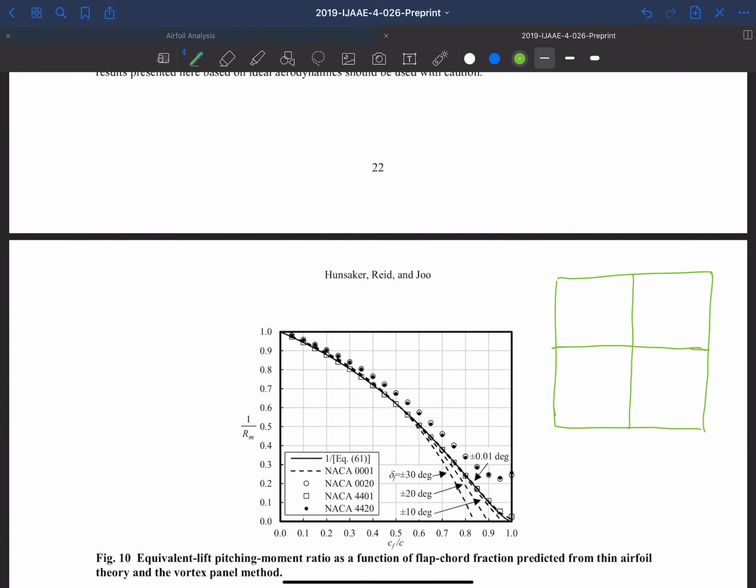But anyway, on the x-axis, we have angle of attack, alpha, and on the y-axis, we had delta for the traditional flap. Okay, and you can look at lift coefficient contours, and they basically look like this. So of course, as we increase our angle of attack, then our lift will increase, and these are increasing up here. So let me draw that here. So our lift is increasing in that direction.